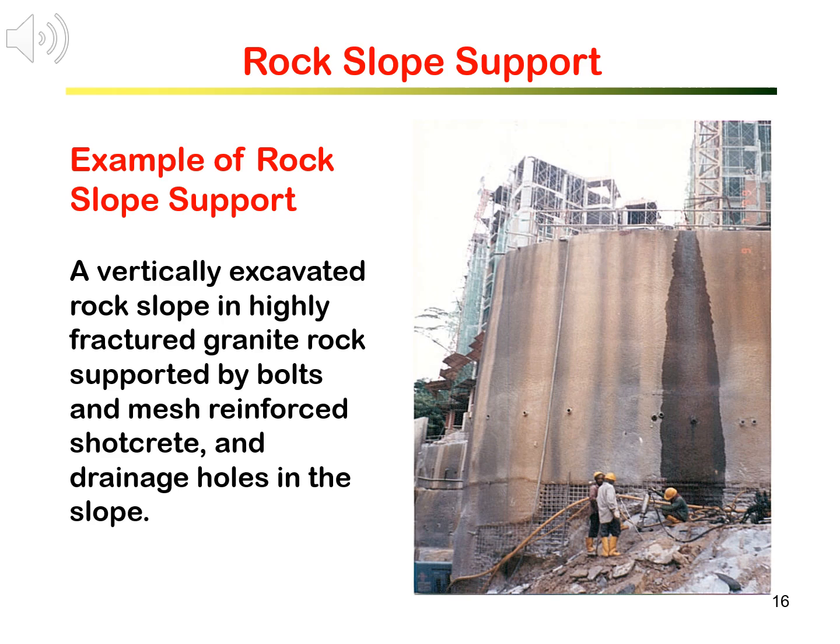The slope is between 10 to 50 meters high. The rock mass forming the slope is highly fractured and partially weathered granite. Assessments were performed using several methods, including mapping, hemisphere projection, and slope mass rating. Slope support design was proposed based on slope rock mass rating, in consideration of site accessibility, slope geometry, and work schedule. In the end, the slope was supported by steel rebar dowels, steel mesh, wire mesh, and 15 centimeter shotcrete. Drainage holes were drilled at the lower part of the slope.